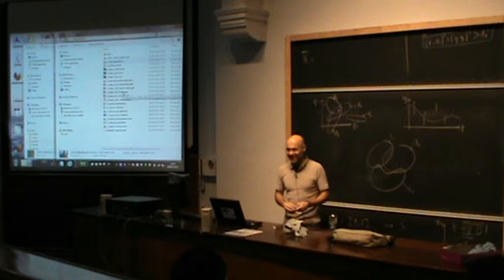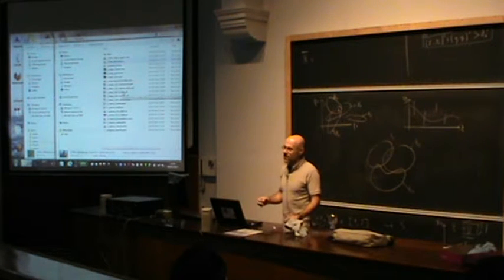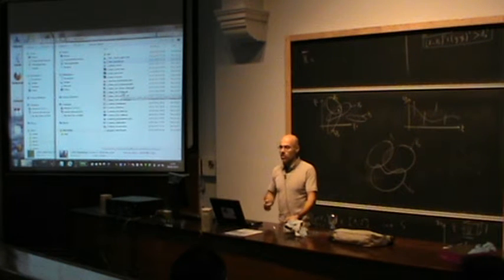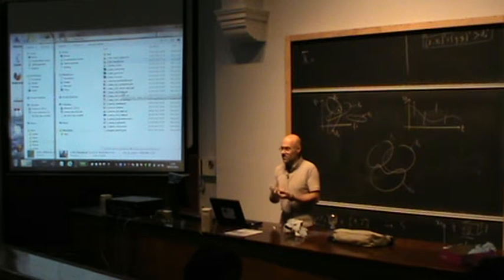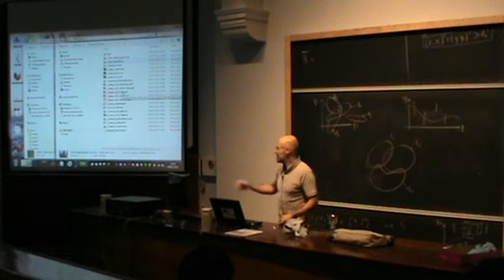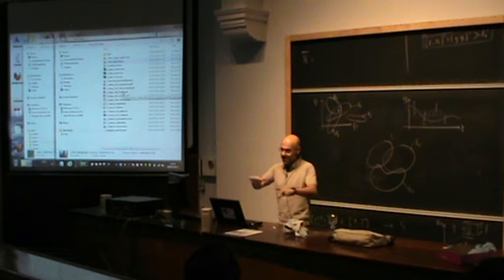I will explain it. But at the moment, it is most of the time a dead reckoning approach. It has a very good compass and a good Doppler, and with the dead reckoning, it knows about where it is, but the accuracy is not that good. So it can be dangerous, and we are not sure that it has inspected the right zone.